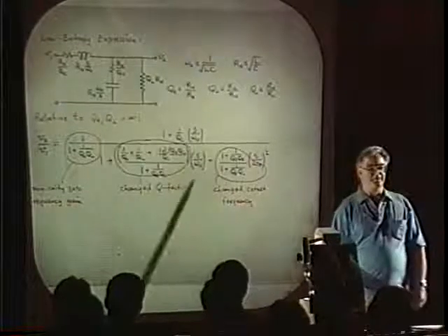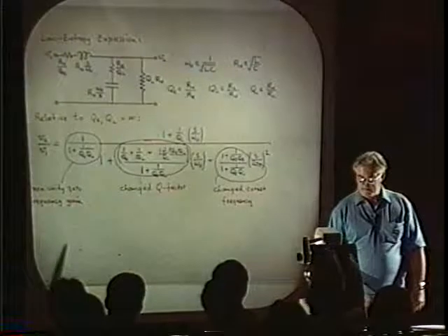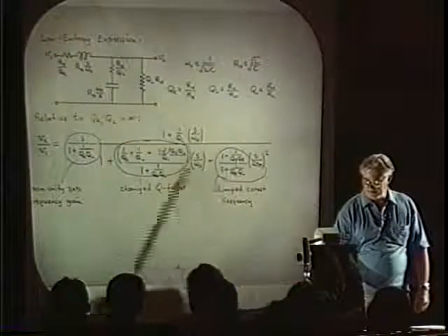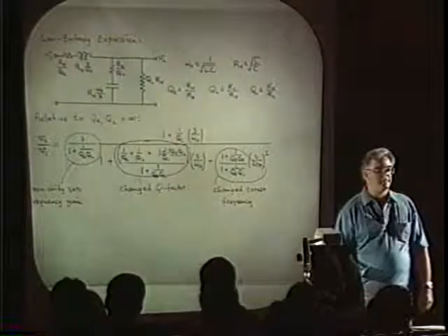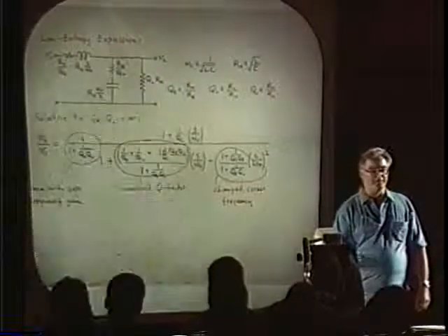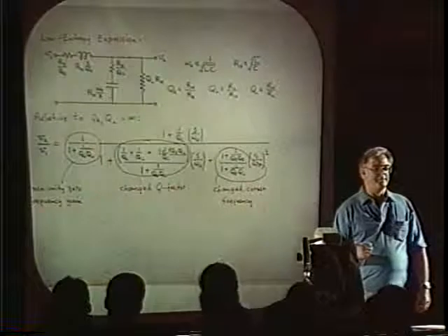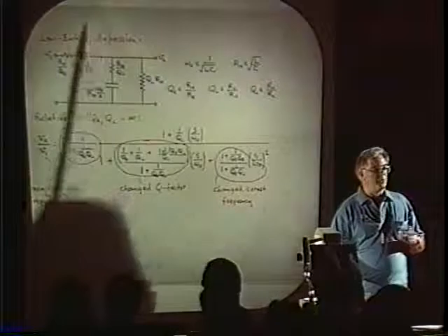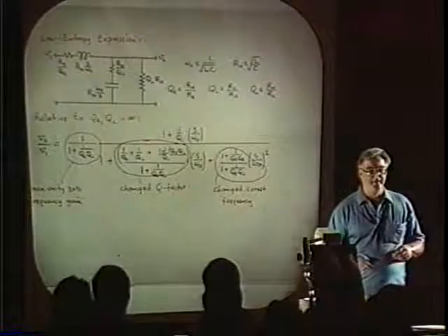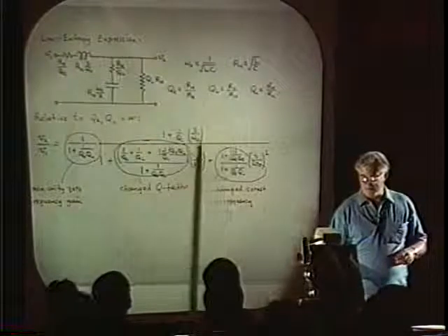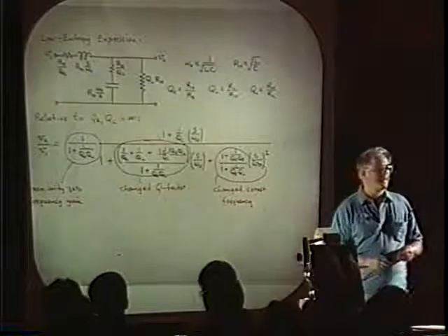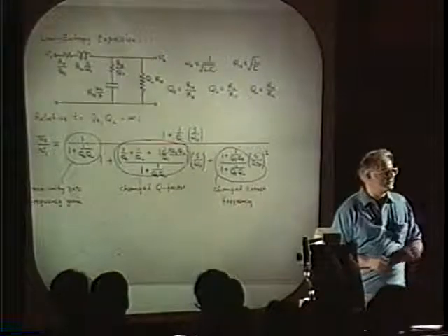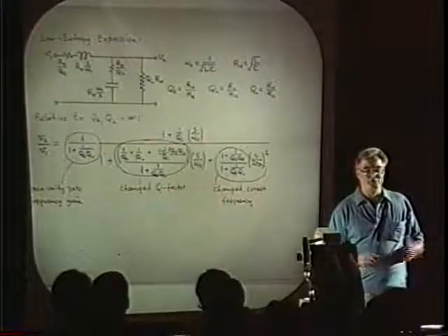But something else useful it tells you is that if there are certain inequalities such that these products of the Q factors are much bigger than 1, which means overall it's a fairly lightly damped circuit. In the case of power electronics, for example, if this is the output filter of a switching power supply, you know all of those Q factors are bigger than 1, because if they aren't, dump the filter. It's no use. It wouldn't be efficient enough.